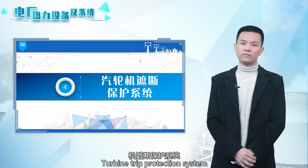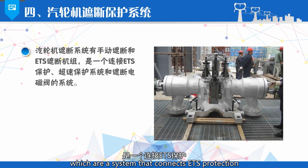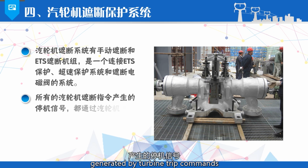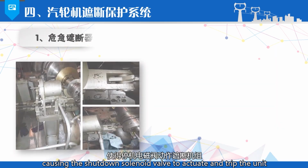Turbine trip system. The turbine trip system includes manual trip and ETS trip units, which connect ETS protection, the overspeed protection system, and the trip solenoid valve. All shutdown signals generated by turbine trip commands are sent through the turbine trip system, causing the shutdown solenoid valve to act and trip the unit.